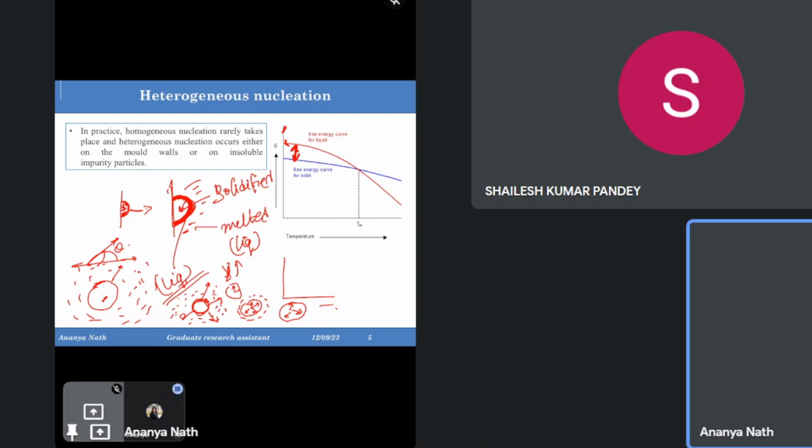So for Ti, we cannot add Ti as it is because titanium is also a reactive material. It can react in a reverse way. So we preferably add some aluminium titanium master alloy, in which the titanium will form some intermetallics inside it. The intermetallics will again give rise to some new strain free grain and grain refinement, as this titanium is giving the nucleus the support to grow and